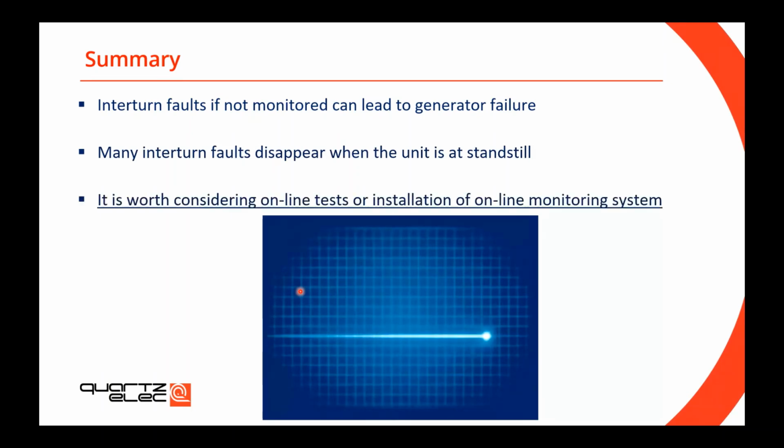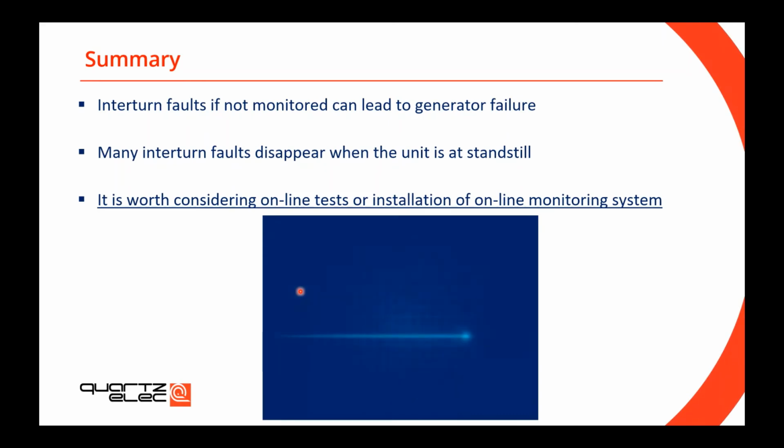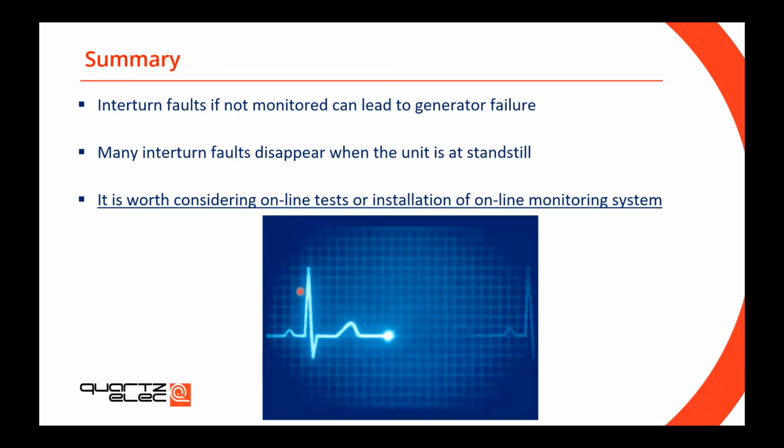And with that in mind, I believe as an engineer that it's really worth considering an online test like the RSO we just showed you, or it's worth considering installation of the online monitoring system, because that will continuously monitor the performance of your generator rotor. And I want to leave you with that thought.